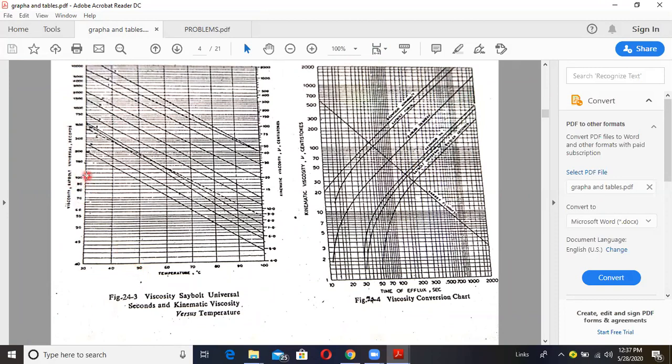Now, from here, move towards the right side like this. Understood? Until it touches, for example, if I take this as 110, move towards the right side until it touches the 50 degree line on the x-axis. Now it is touching here, right? Here it is 50 degrees, and again here it is 110 on the y-axis. Now here we got the intersection point. For this intersection point, note down which curve we are having. That is nothing but curve B. Right? Curve B we are having.